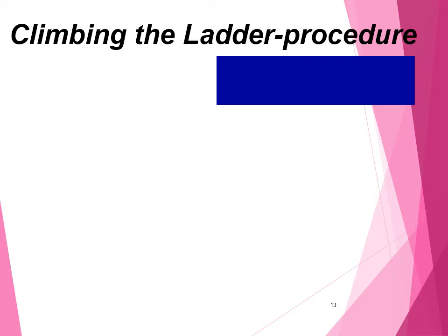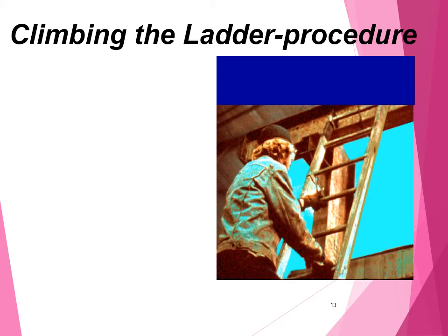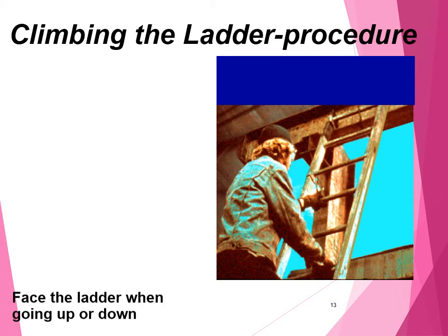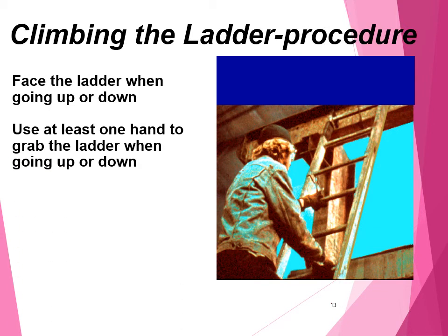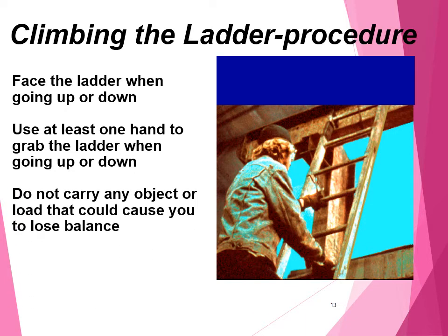Climbing up the ladder procedures. Always face the ladder while climbing up. Use at least one hand to grab the ladder when going up or down. Do not carry any object or load that could cause you imbalance.